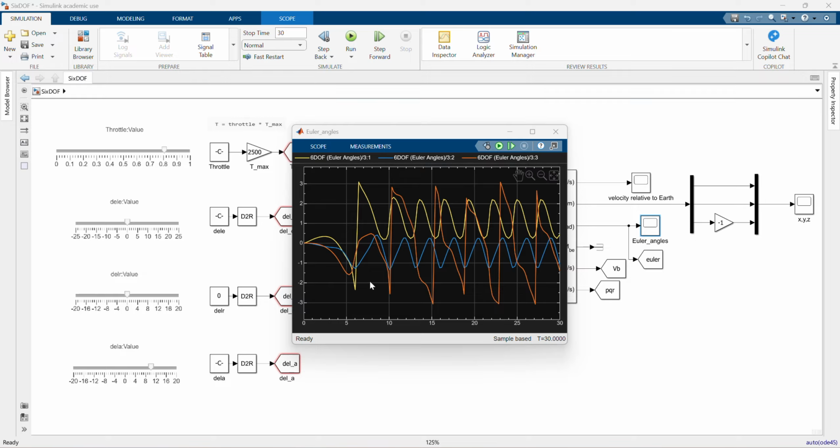But if you look at the other things, it is showing a big change with the roll. What's unique is this is also showing you the coupling I was talking about, the rudder to aileron coupling, or yaw to roll coupling, or roll to yaw coupling. This orange one is the psi, or your yaw angle, and that one is also changing, but we did not give any yaw input in this, and that is because of the coupling happening. So that's a good thing to see.